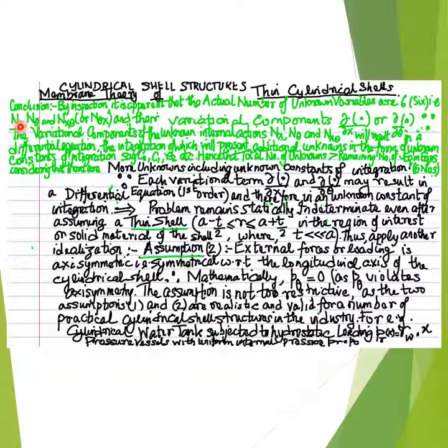that there are only three unknown internal in-plane or membrane actions that remain to be solved after the application of the statical force and moment equilibrium equations and the thin shell assumption to the differential thin cylindrical shell element presented in the figure in one of the earlier slides,